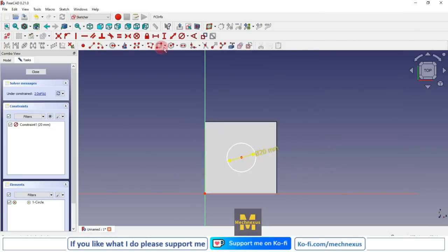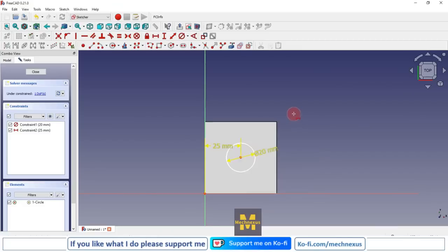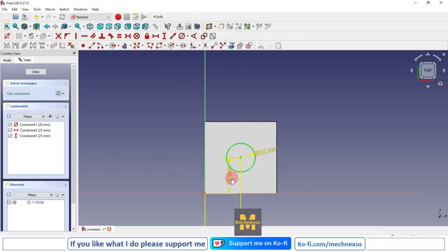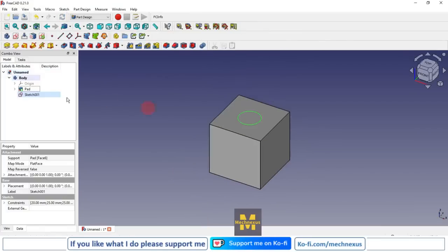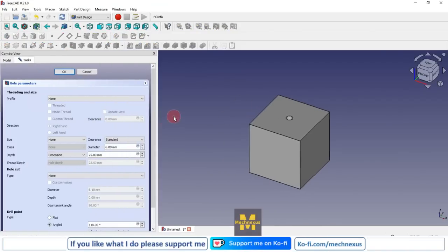And let's give the dimension and constrain it. So horizontal dimension 25 and vertical dimension 25, and I move it and I close it. Now we will click on the hole feature and we will see the options available.